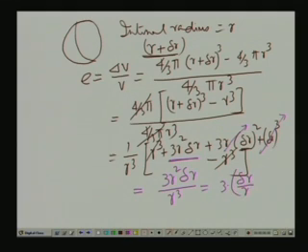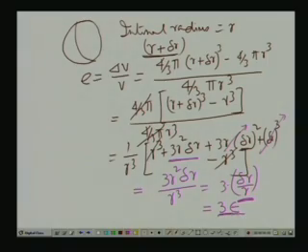And again, as you can see, delta r by r is the radial strain. That means delta r is the elongation in the radial direction, and that divided by the original radius will give you the strain. So, this is nothing but equal to 3 times epsilon. So, E, the volumetric strain, equals 3 times the normal strain.